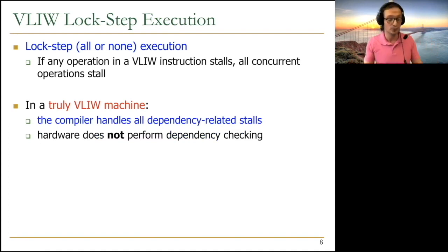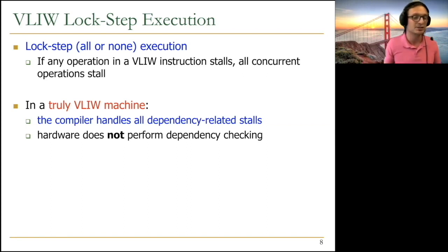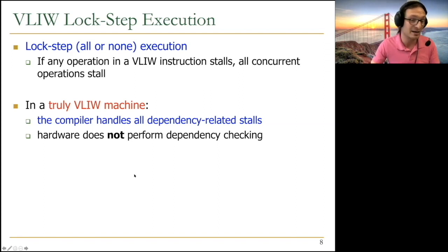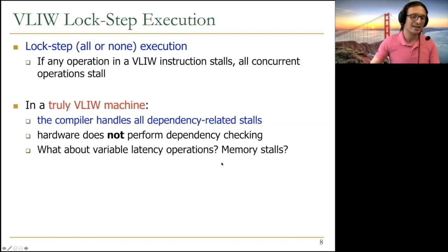This actually includes dependency checking between pipeline stages as well, not just within a pipeline stage, but also between pipeline stages. So the philosophy is actually very similar to simple reduced instruction set computers, right? Simple instructions. Hardware is simple, compiler is complex. But of course, life is not as beautiful.